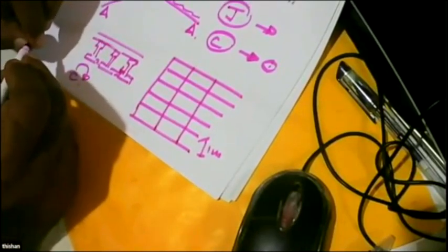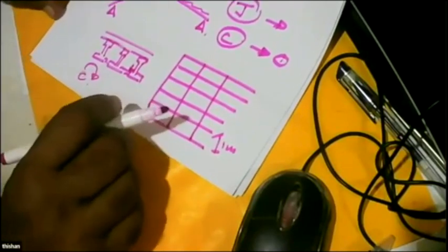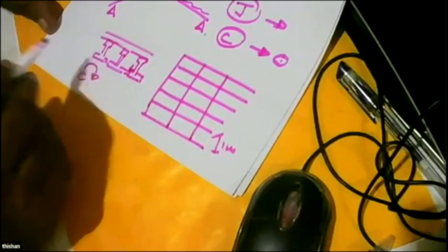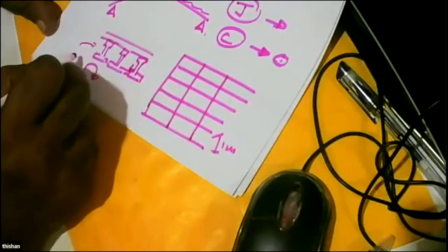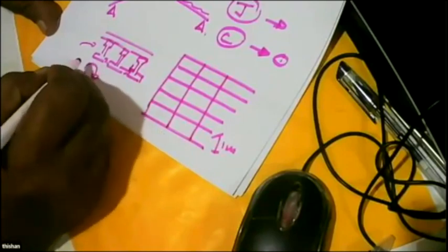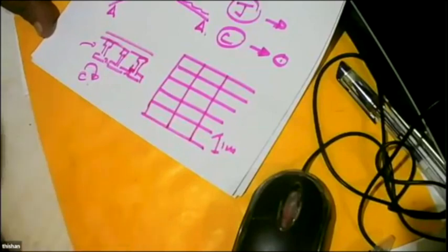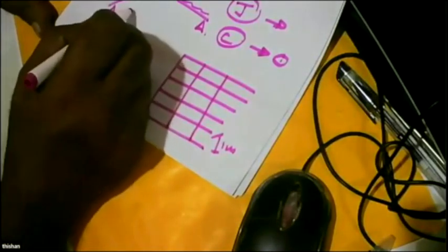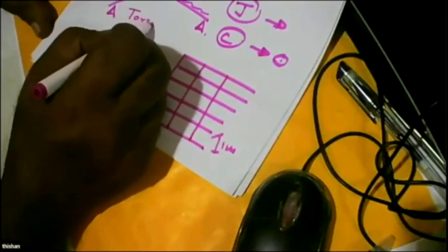But what will happen if you apply that? Then when you analyze, you will find, because you have allocated the value C, now this is attracting more moment, and you need a bigger section to resist. So it goes on like that. You assign a value, then it says, okay, I need a bigger value. So because of those reasons, we say, let's analyze it as a torsionless system.